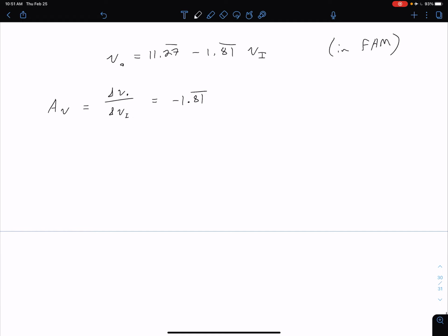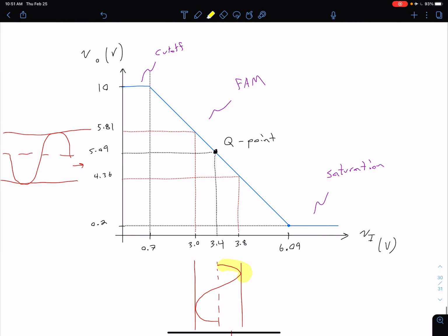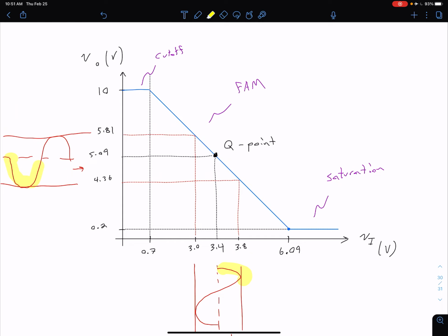And so again, to be more specific, if we talk about our output peak to peak, V output peak to peak is approximately 1.45 using those values above. And by definition, because we had that small signal input source, our input peak-to-peak voltage is 0.8 volts. And of course, we could take the ratio of those, and we would see that that works out to be a magnitude of 1.81. And of course, the negative sign just comes in with the phase difference. So when this curve is increasing, this curve is decreasing. So that's where the negative sign comes in.